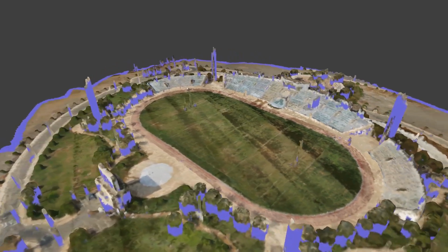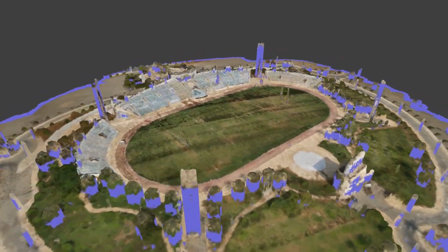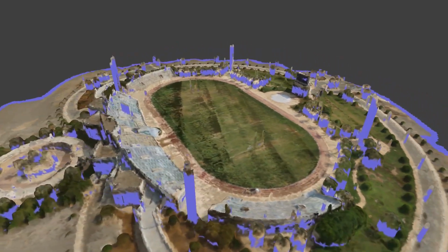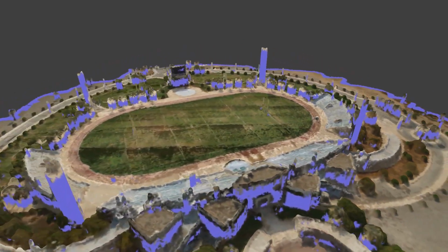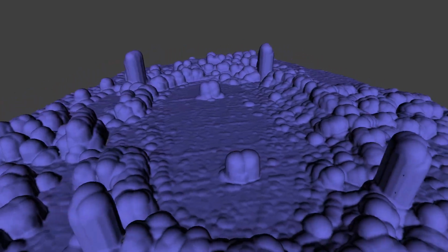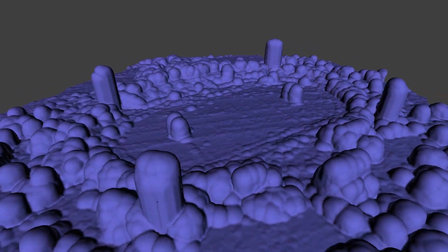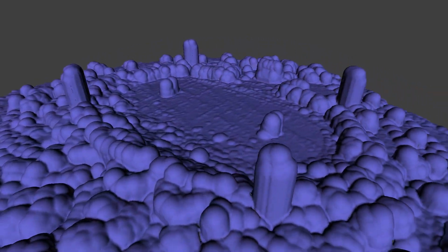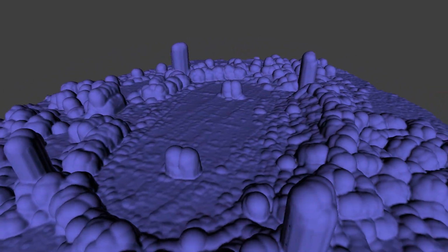We first reconstruct from 100-meter altitude nadir views with high forward and side overlap. From the capture, we generate a geometric scene proxy mesh. We then compute a safe flyable airspace from the proxy that prevents the UAV from flying closer than 2.5 meters.